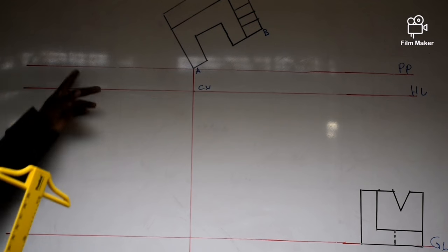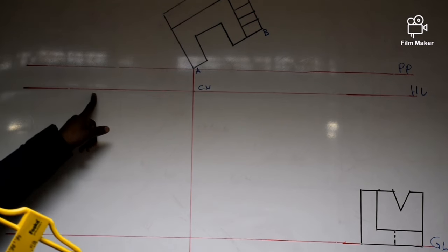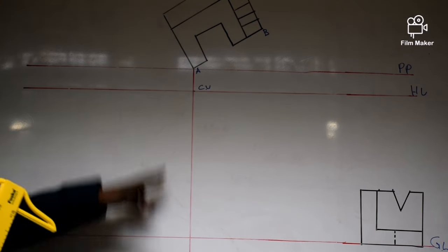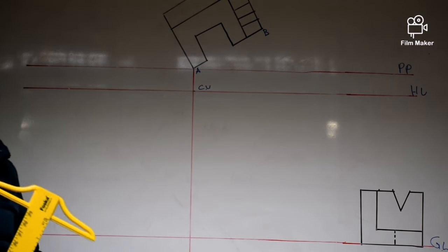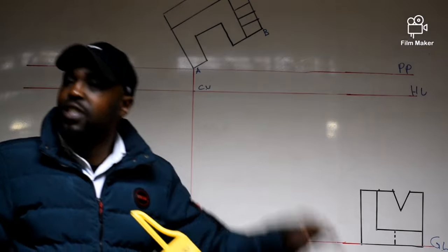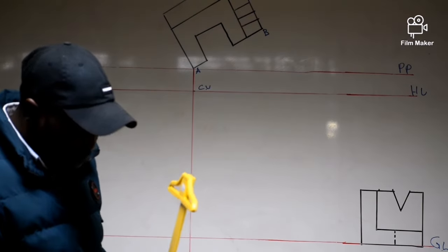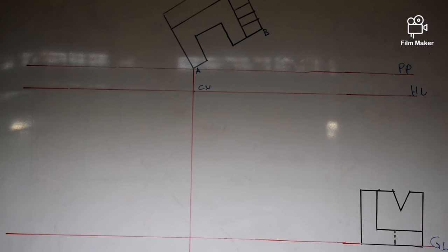And you know from there till there is 20 millimeters. And then from where your 20 millimeters ends, the distance of an eye in front of the picture plane, which they said is 100 millimeters, will give you the stationary point. The ground line will be there altogether. So now we are going to take a drawing canvas. Actually, not a drawing canvas. I'm used to a drawing canvas now.